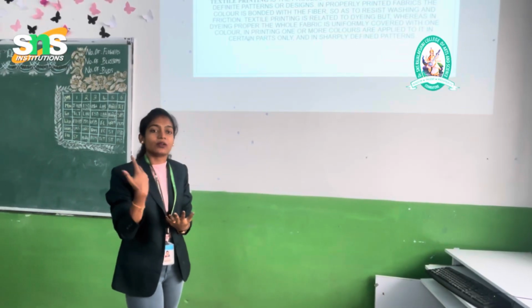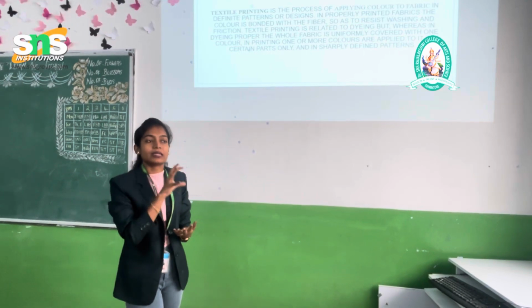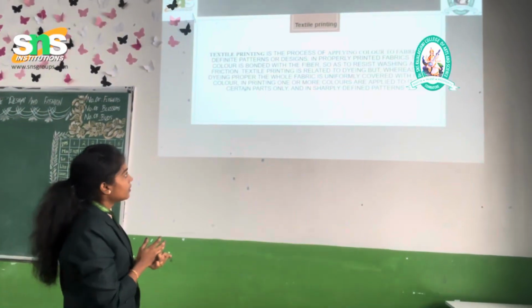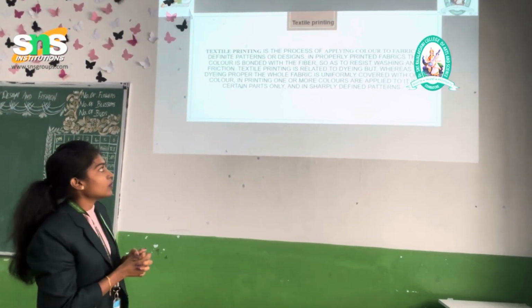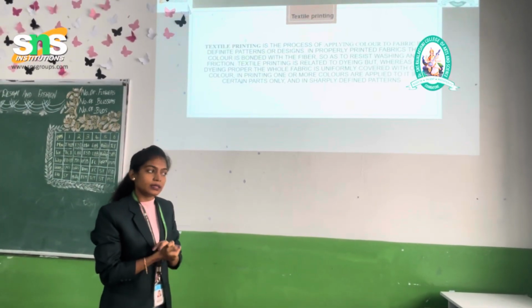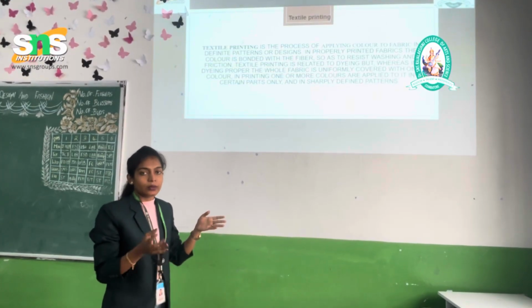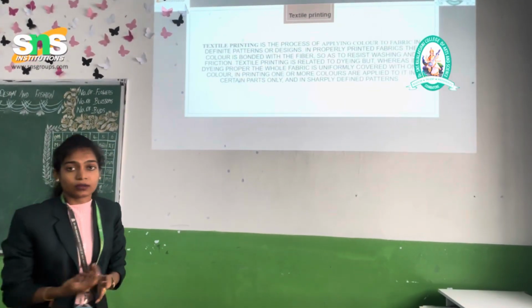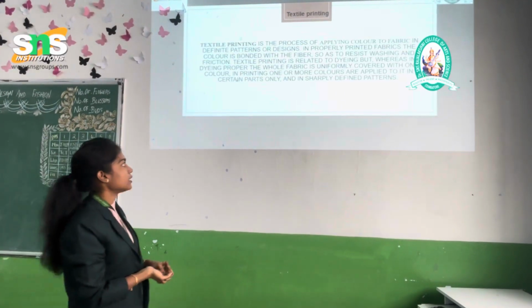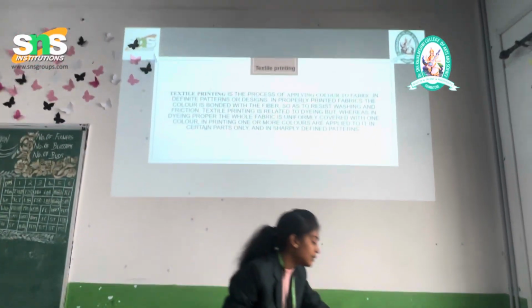When we're talking about printing method, this is how the design gets onto the fabric. Let me briefly mention a few popular techniques like block printing, screen printing, roller printing, heat transfer printing, and digital printing. Digital printing is the most modern method. It works like an inkjet printer, directly printing the design onto the fabric. It allows for detailed, colorful images and is perfect for small batches or custom work. And now let's not forget the final step, which includes drying and fixation, often using steam or heat.